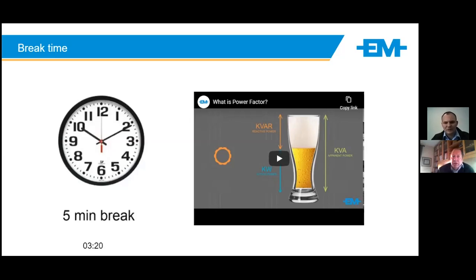Then there's a question in terms of the bearings of the motors. What are the measures to put in place to take care of the harmonics caused by the speed drives on bearings of electric motors? Are there instances where the speed drives are totally unwanted to the extent of using traditional motor starters like the DOL or Star Delta or auto transformer?